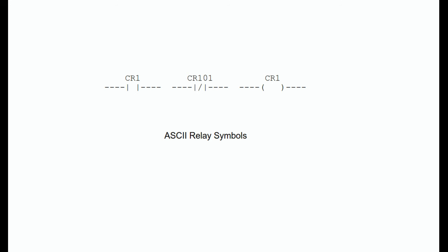Relays can range in size from extremely small reed relays in 14-pin DIP integrated circuit style packages capable of switching a few tenths of an ampere at less than 100 volts to large contactors the size of a room capable of switching thousands of amperes at thousands of volts. However, for electrical machine diagrams, the schematic symbol for a relay is the same regardless of the relay's size.